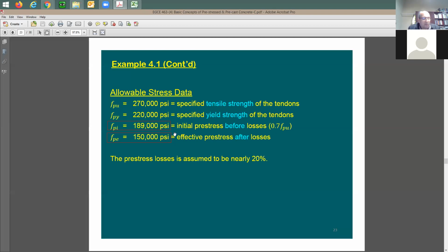So at the beginning, we're not going to be at 100% of the concrete strength, which is kind of critical. You wish, of course, that you wait for the full strength of the concrete, and then after that you apply this high stress in the steel, and therefore it is also applied to the concrete. So the tricky part is that you apply this 189 KSI in the strand, and at the same time the concrete strength is not at the perfect level that you'd like to see it at.